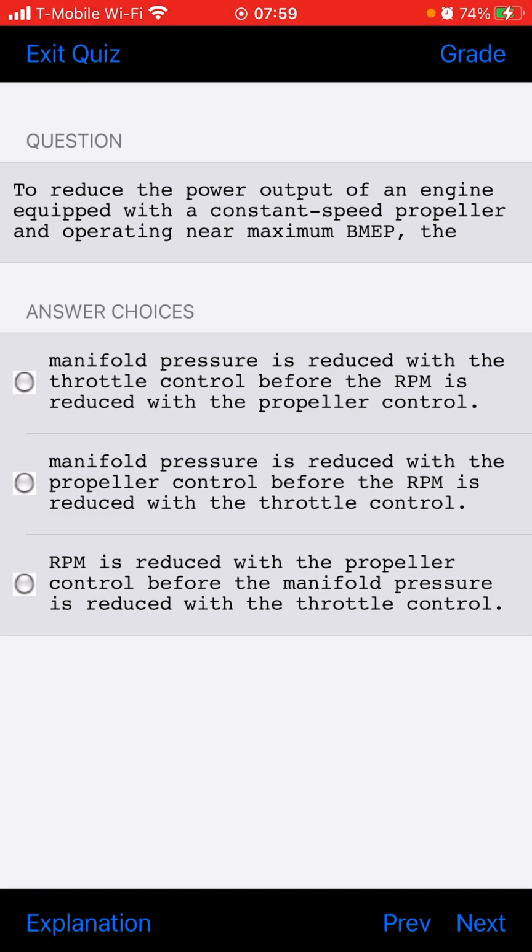What should be done to repair a loose stud in the engine crankcase? Well, first of all, you want to remove the stud and inspect the hole for size and condition of the thread. It may be necessary to use a suitable oversized stud.